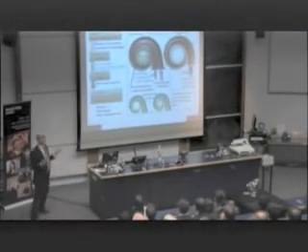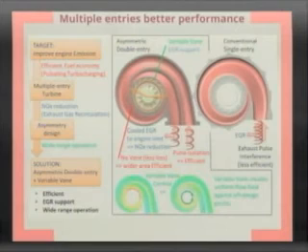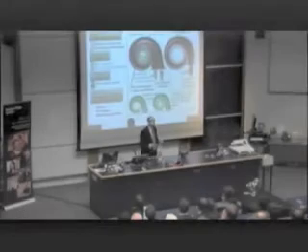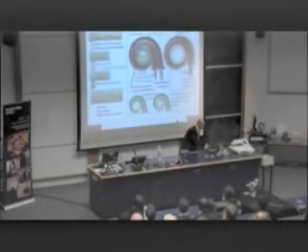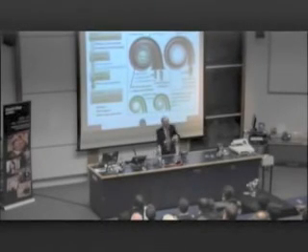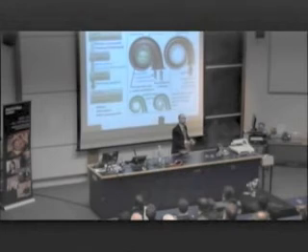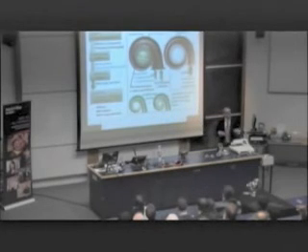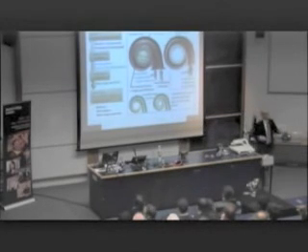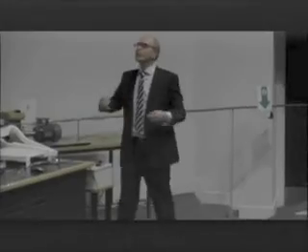Another innovation, I'm getting to the end. Very many times with engines, you need to take some gas before it enters the turbine. This is the wheel, the rotor I've been holding in my hand, and do something else with it. It's called exhaust gas recirculation, and you want to put it back into the inlet. This is the strangest thing I've ever seen. But you take the exhaust and put it back into the inlet, into the combustion chamber again. So it's a bit odd. But if you look at the emissions, NOx particularly, these things are improved when you do so.